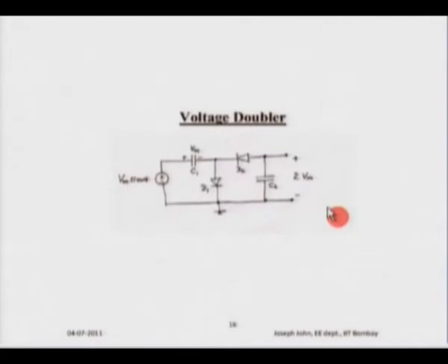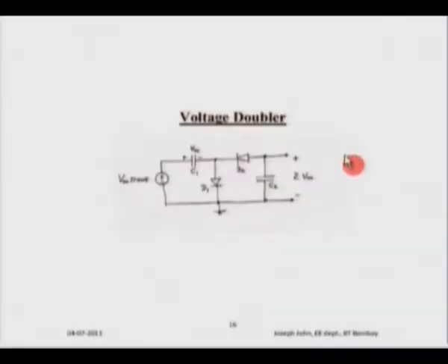So, these circuits are very useful, especially voltage doubler circuits are used in oscilloscopes and also in television sets, where you need to have very large voltages, especially the plate voltage in a CRO or in a television requires voltage of the order of 10,000s. So, voltage doublers are very useful. In this circuit, the moment you put a resistor, you would see that the voltages slightly change, and in most voltage doubler applications, the current drawn would be very small.